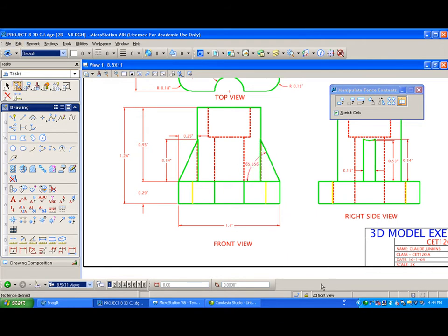That's why that didn't. When I was trying to figure out what was going on, I turned the association off when I turned that. Otherwise it would actually change the angle. So that's how it works. So you want the dimensions to be associated with the object. So if you do go make a change on something, everything changes, including your 2D elements. Alright, good.